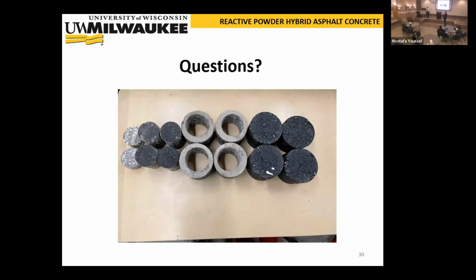I think so. I mean, you cannot do that with the cement paste. You can do that with grains. So, if I understood your question correctly, as we are producing these mixes, the temperatures for mixing and compaction were 135 degrees for mixing and 115 degrees for compaction, enough to do the job, especially with a warm mix additive. That's in part why we wanted to have a low energy mix that is also self-healing.